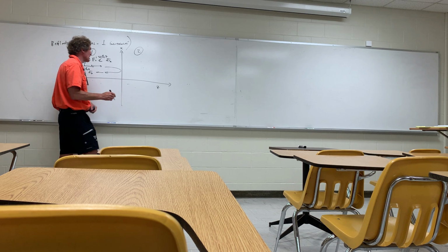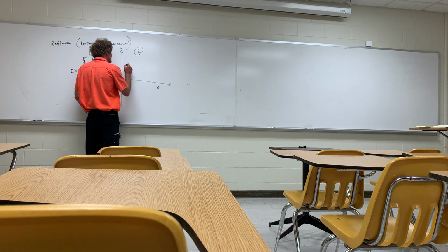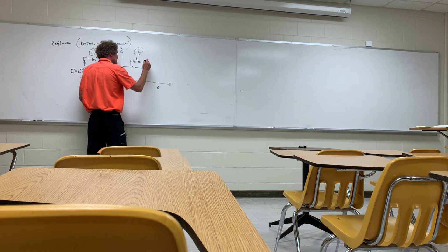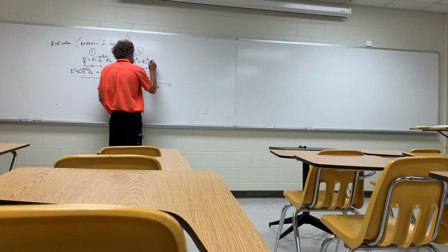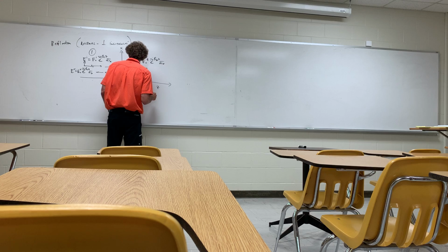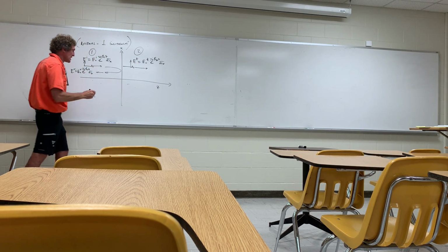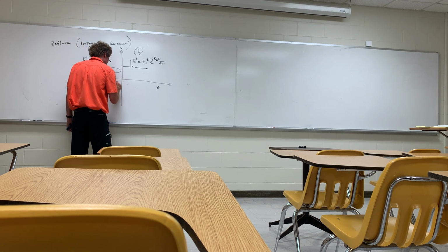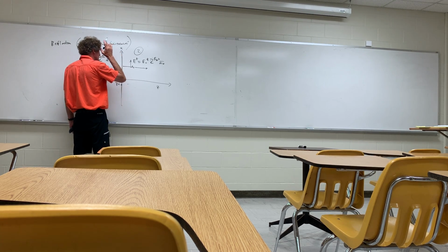But you'll also have some that actually propagates through. So you're going to have an electromagnetic field that is transmitted, and E transmitted is E naught transmitted times e to the minus j beta 2 z in the a_x direction. Now those are the electric field quantities, and I'm going to make this interface between the two regions be at z equals 0 to make things easier.